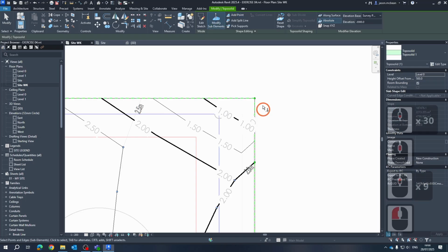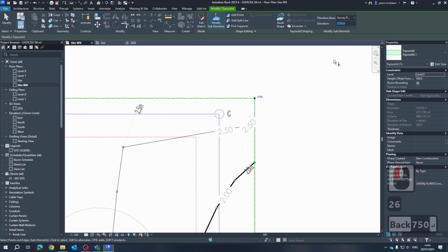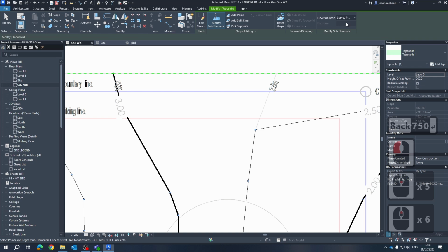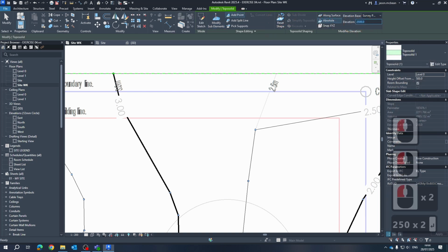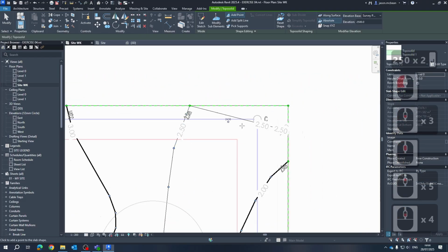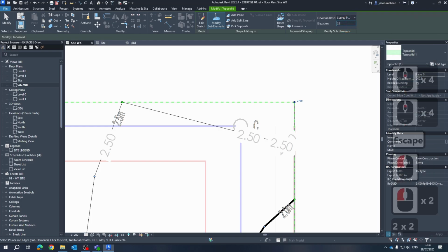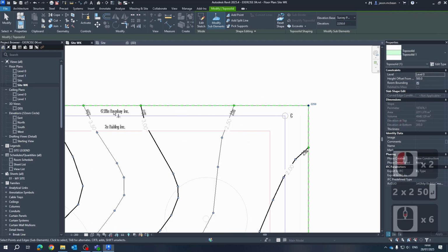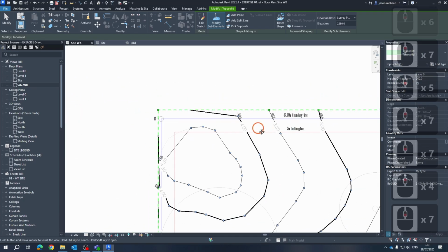This point over here, so go to edit point. That point is going to be between 2 and 2.5, so I typically round it off, so it'll be 2600 or 2750. Fixed. Okay, add point, 2500. Good, so you can see we're adding these. That should be, so 2250 maybe, sorted that out. So we've got our 3 meter point there, that worked well. We've got our 3.5, that worked well.